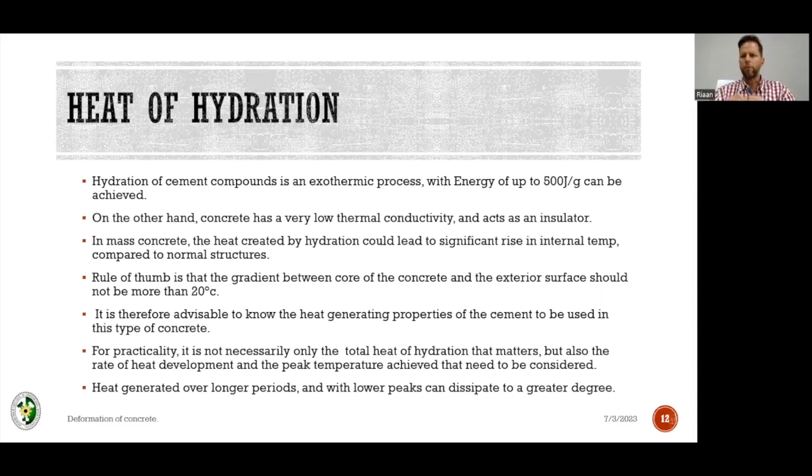And sure as Bob, these trucks started cooling down. They went up to about 32, 33 degrees. And then after a few minutes, you see the temperatures lowering. So as soon as it went below 30, the trucks were dispatched to site. And when they got to site, easily achieved 25 degrees centigrade, which then conforms to the temperature requirement of the